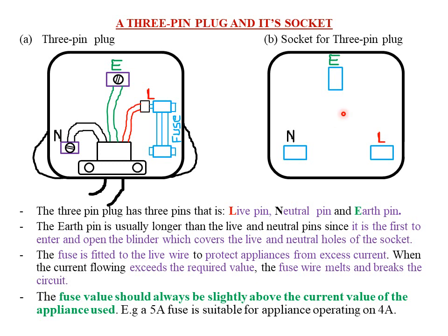So in most cases, when you find the charger of a laptop or maybe the charger of a television not effective, the main reason is usually that the fuse has blown out. So what you do, you just purchase another fuse, then fix it there, then you'll see your charger will start functioning normally. So these are very important points that examiners like.